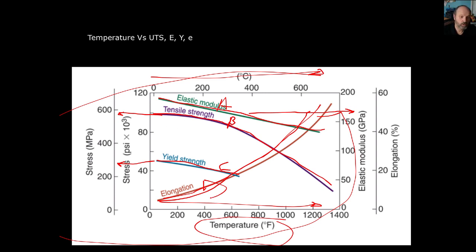And it is important. You might say, well, tensile strength and yield strength, I don't know which way it goes. Tensile strength is, if you remember the stress-strain curve, it's more or less linear, and then it goes into the plastic region and then comes down and breaks. Okay, the tensile strength is up here. The ultimate tensile strength is at the peak.